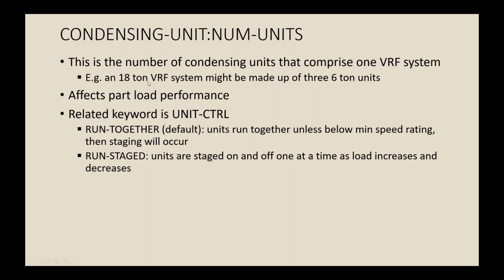For example, you might have a 18-ton VRF system made up of 3 6-ton units. So you would have num units equals 3. And the importance of this is it affects the part load performance in the model and staging of those compressors.